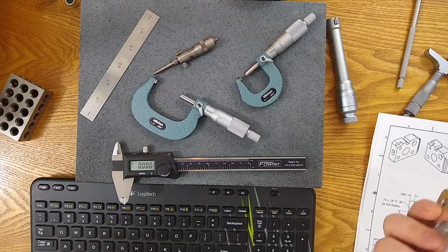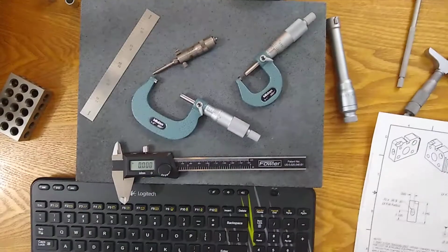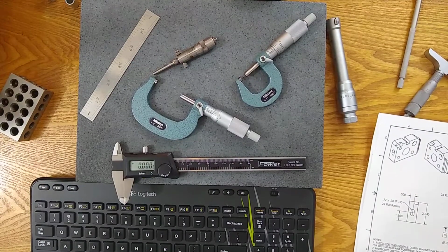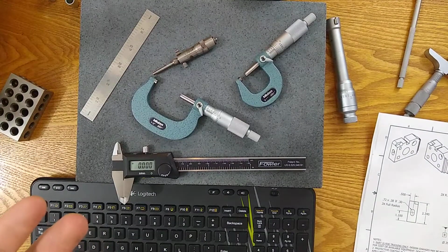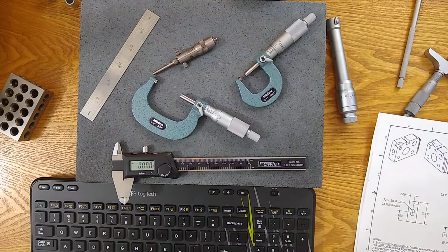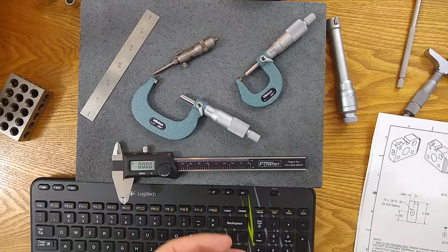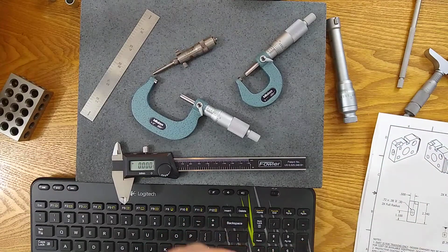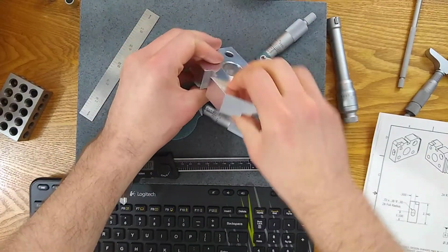Consider if fixtures will help or hurt. Sometimes setting up complicated fixtures you think will help you, and by the time you do it, you're like, this isn't helping. Maybe this is introducing a new error. I've seen a number of people tell me, oh yeah, I'm looking at the part. We're both looking at the part. He's like, oh yeah, I'm going to set it up and hold it and twist it.